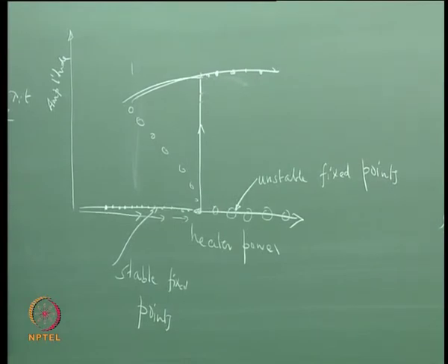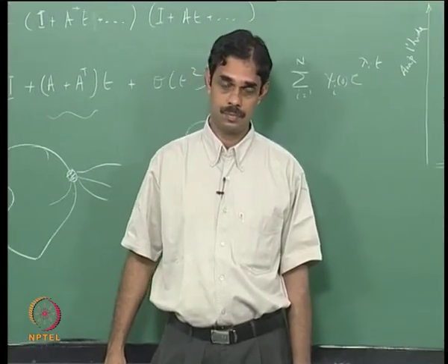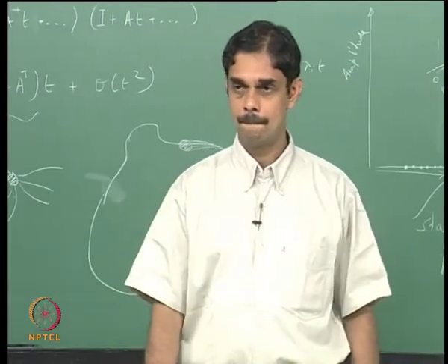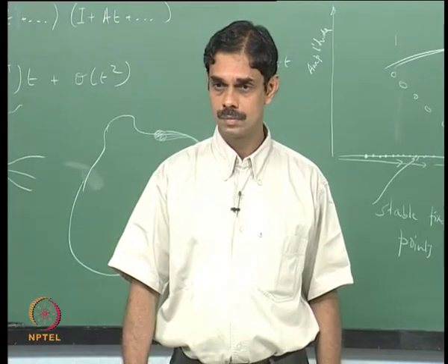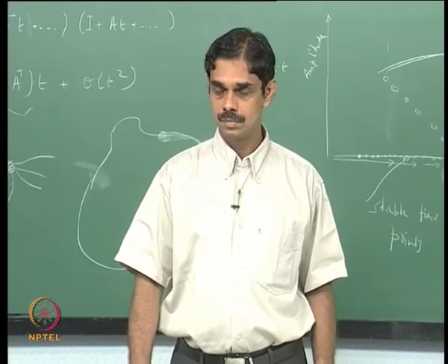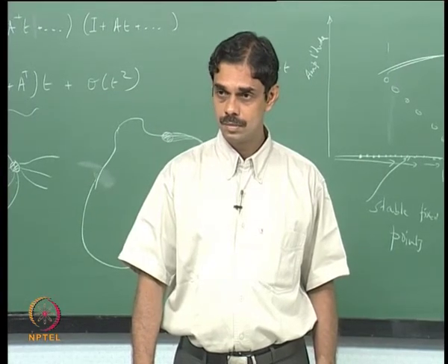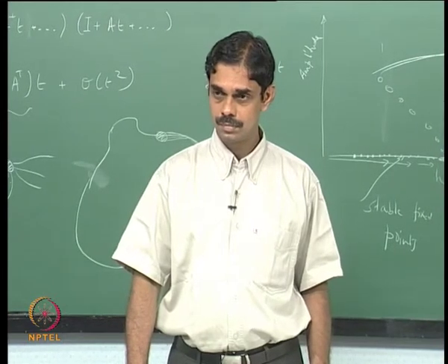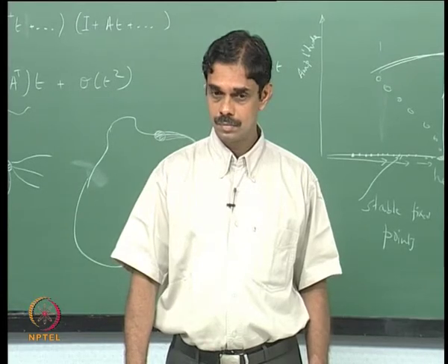Suppose in the system I am just taking the gas and not the heater, the heater power taken in by the gas is plotted here. So in that case, once it goes to the unstable mode, it will take in more power now, because the amplitude of vibrations here is high. So from the heater, the power absorbed into the gas will be much more in the unstable mode than in the stable.